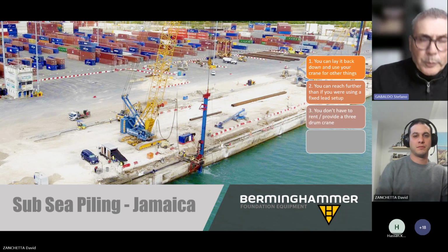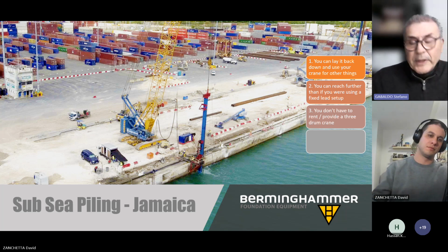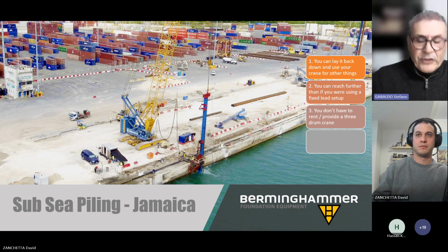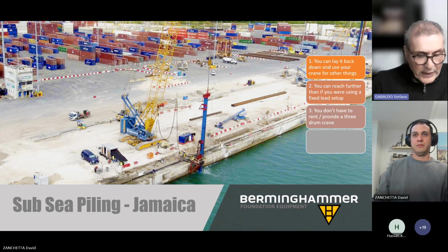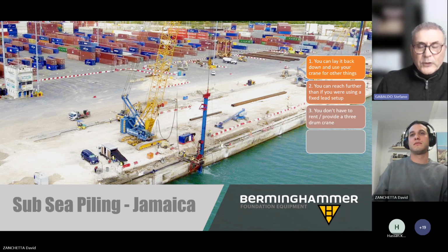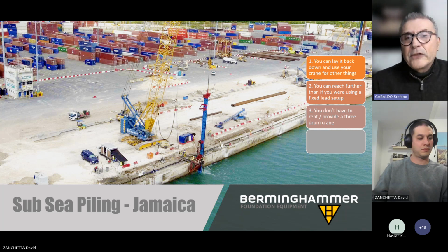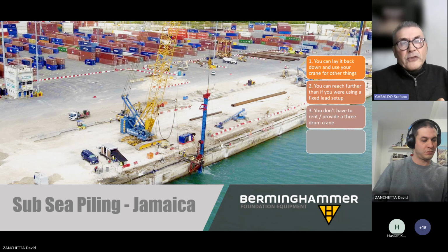Basically, they wanted to bring bigger ships. Bigger ships means a bigger draft. When you bring bigger drafts, you need to have dredging. And the moment that you add dredging in front of an existing structure, you're required to put in some sort of a buffer construction in order to separate the existing soil elevation with the new dredge seabed elevation.